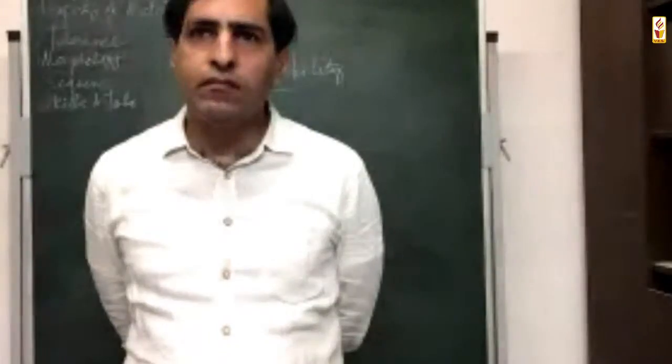So there is a question on Google chat: is the heat gain of ferrocement more than conventional brick? Yes, it is quite a lot, and for that we use certain techniques like putting China mosaic on top, the height of the room, and cross ventilation, getting hot air out from the upper level, which becomes very, very important. Still, I will agree that it is quite hot, and we are working on it.